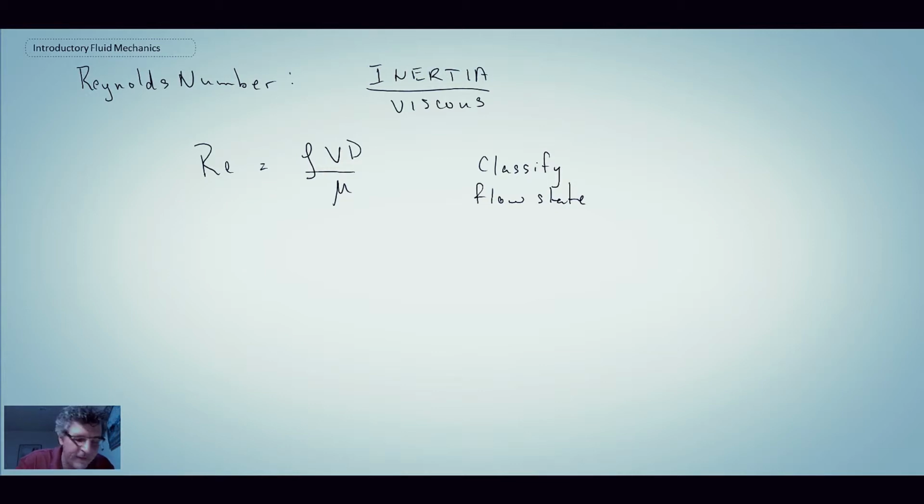Typically, as a rule of thumb, a low Reynolds number, although low is relative and depends upon the type of flow that you're looking at, be it flow over a cylinder, a sphere, or a flat plate, because there the characteristic dimension will change. But typically, if it's a low Reynolds number for the application, the flow would be laminar. And if it's a higher Reynolds number, it could be turbulent. And between the two, you go through a transition zone. But again, exactly what low and high mean depends upon the nature of the flow field that you're looking at. So that is the Reynolds number.